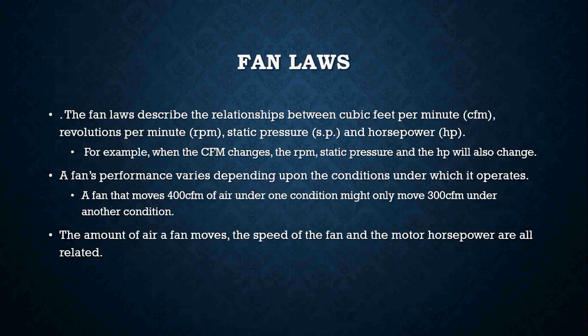So if a furnace isn't getting enough CFMs across the heat exchanger, I run the risk of overheating my heat exchanger, maybe possibly hitting a high limit switch because I'm just not moving enough air, right? Or if it's going too fast, I'm cooling the air off too quickly and I'm not going to achieve my correct temperature difference, which means the furnace is going to run longer.